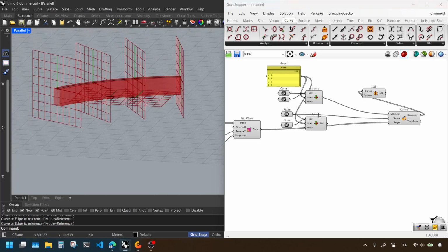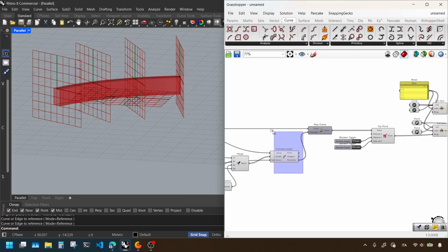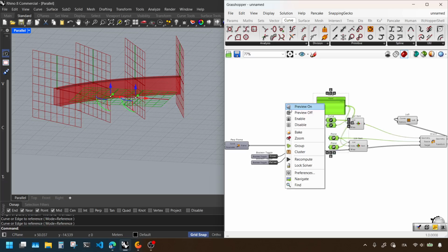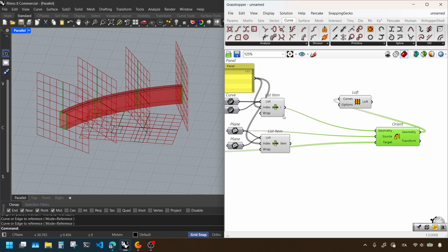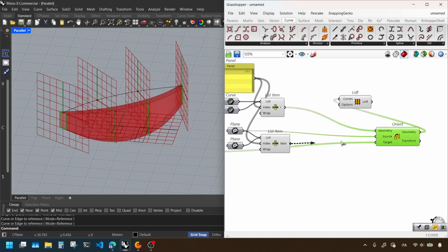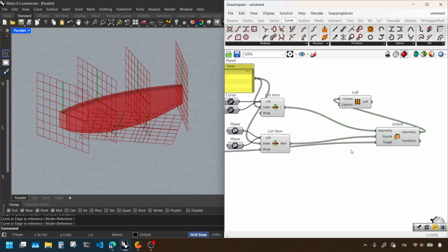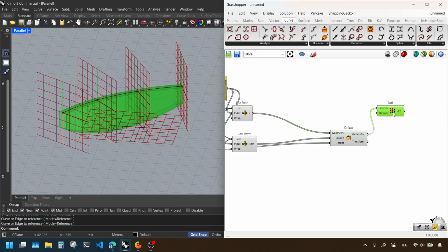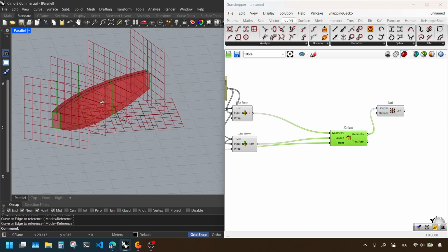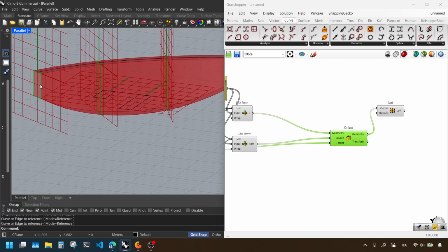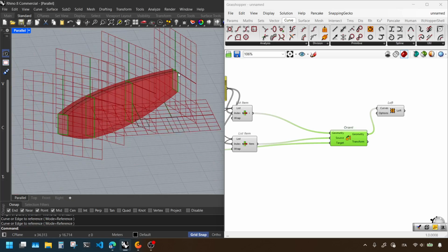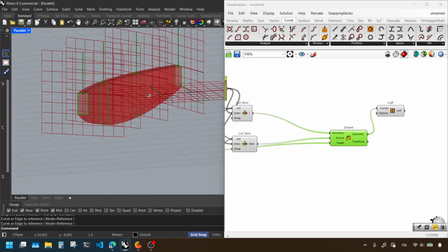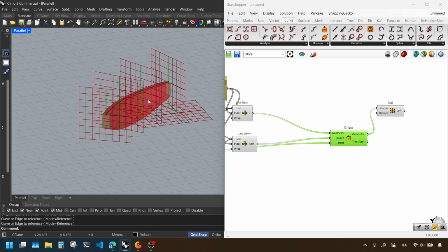Okay, we should now see the correct sections positioned. Let me see, source geometry. Well, we have to plug in the correct geometry and the correct source planes. Instead, in fact, we do have it now. And now you see we have a first section, which is this height, then the two middle sections, which are higher, and then the last section, which is smaller. And we can't do this with the sweep, but with the loft, we can.